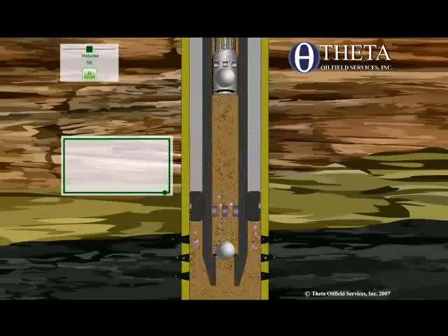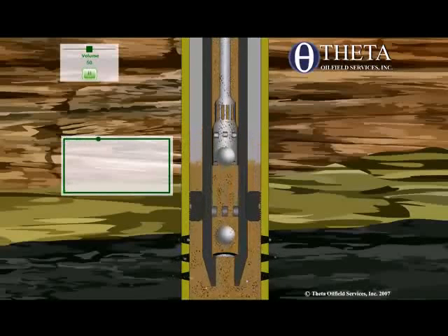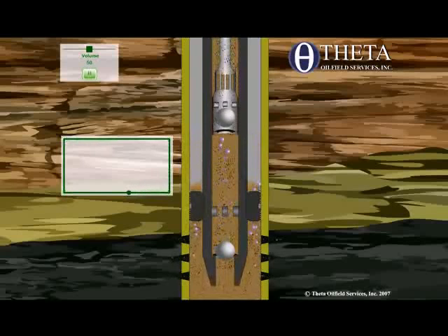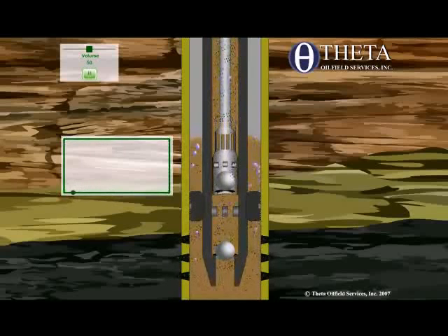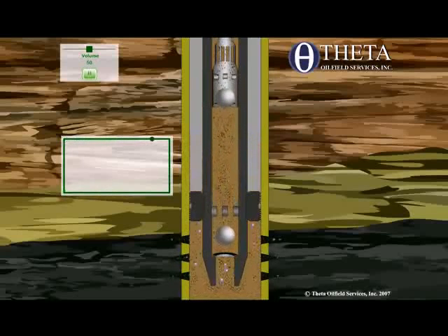You can see the gas coming out of the perforations. I can look at the traveling valve and how that works. Are the gas bubbles getting larger? Yeah, which is what actually happens, right? Because they collect, they merge together? No, as the pressure goes down, they get bigger.